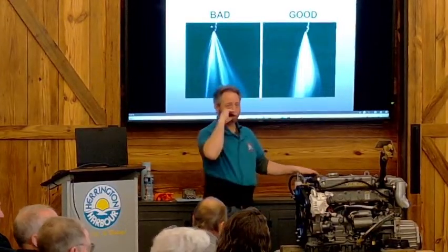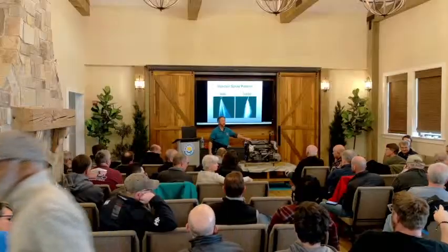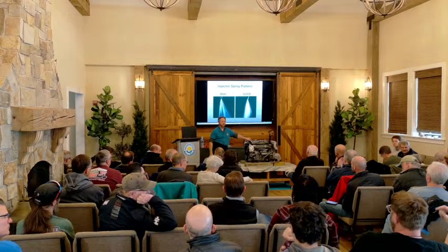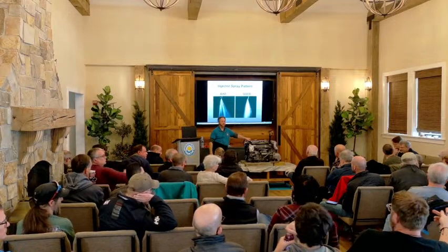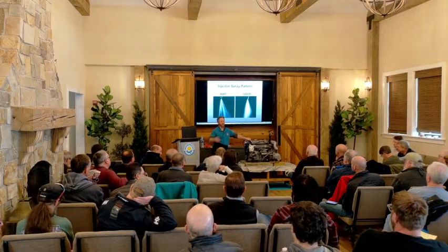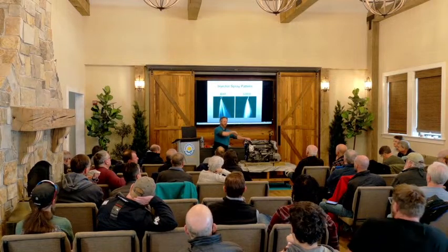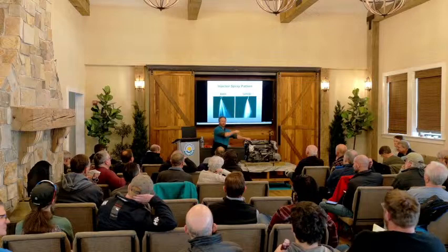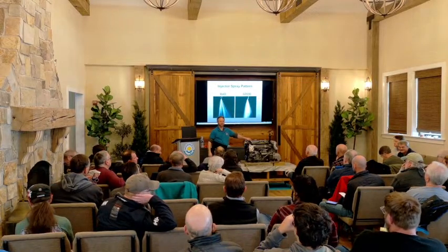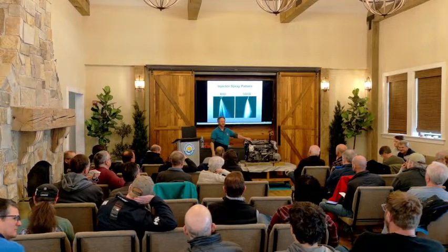But I think what he's saying is, you only winterize yours down to 20 degrees, right? You only winterize this to go to 20 degrees as far as outside temperature. So he's asking, since the temperature got colder than 20, does he... Well, that's the part my brain doesn't work around, because I just buy it and I pour it in. There is no dilution. The engine dilutes it as it's traveling through the raw water cycle. I just buy the West Marine -50 and dump it in, same with my fresh water tank. I don't know, so he's asking, does he need to worry?